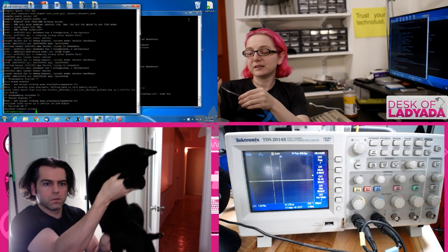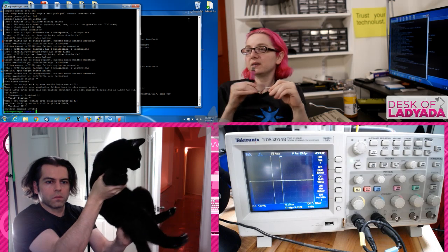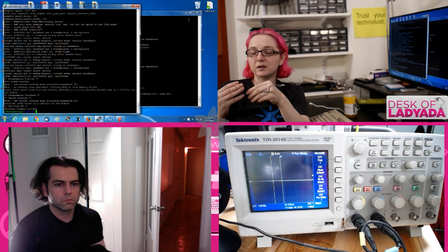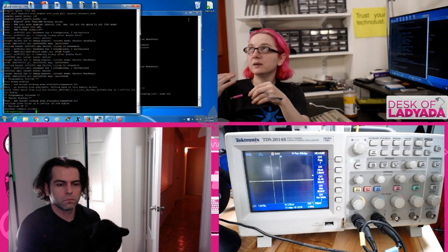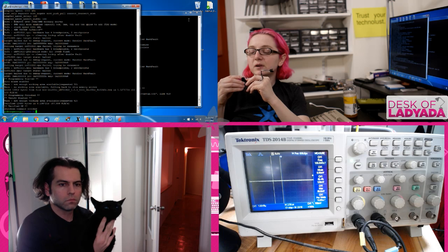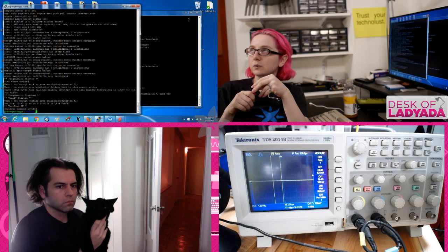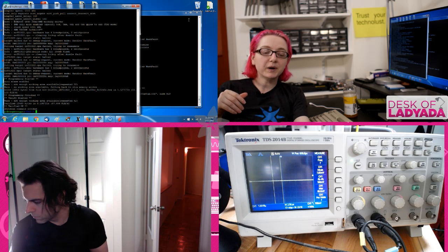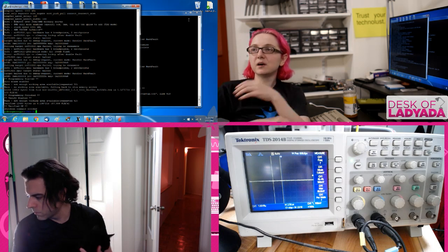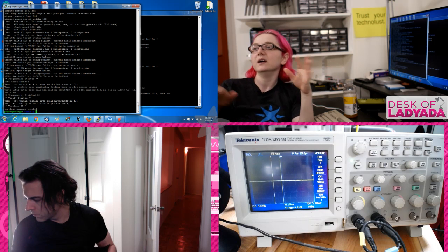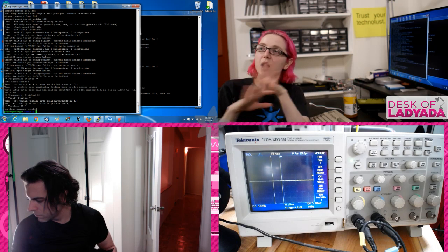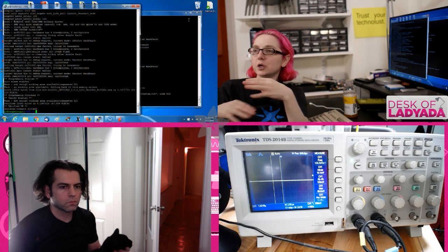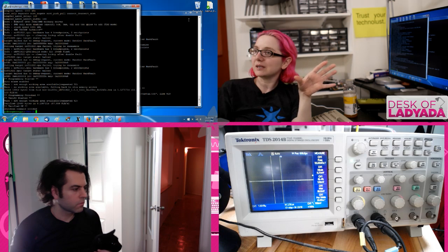I actually really like them, and we have like 20 testers, so I could get a bunch of J-Links and then rewrite all the code, but I thought, you know what, I've noticed that you can make testers that are based on laptops, but eventually you want to transition away from that to something standalone. If it's a Raspberry Pi, you can make 6 of these and just clone the SD card, and it's identical hardware and an identical software setup. It's not going to auto update, it's not going to install Windows 10, it's not going to get malware, it's not going to go on the internet. It's clean.